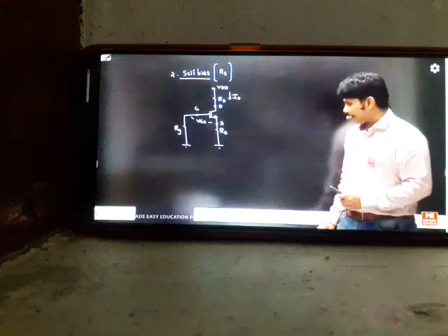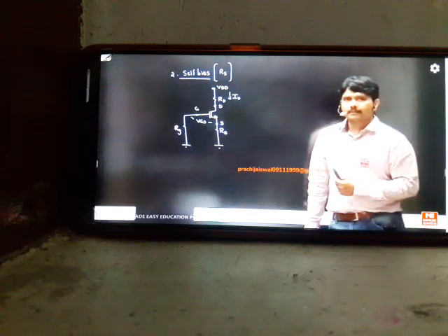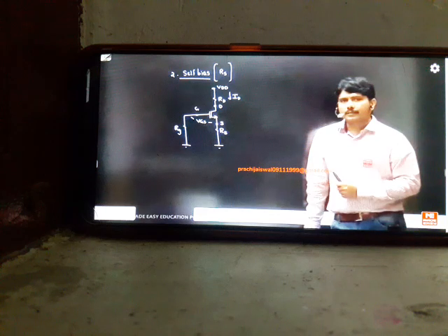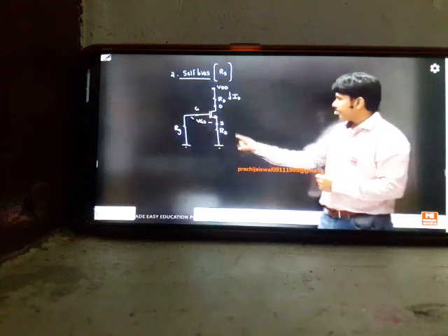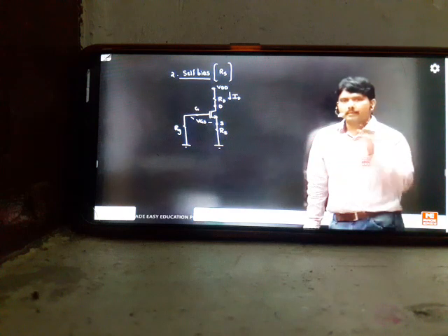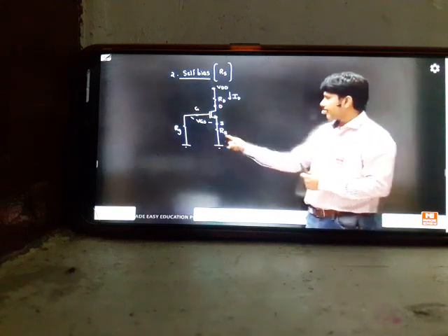See the diagram, you'll understand clearly. See your notes, your diagram, fixed biasing. The difference you are observing is very important. In fixed bias, we don't have RS, correct? We have taken a direct short in the fixed biasing technique. But in self bias, RS is important because RS will play the role of negative feedback. In the BJT class, RE plays the negative feedback. In the MOSFET class, RS will play the negative feedback. So this is called self bias, the name we can tell.